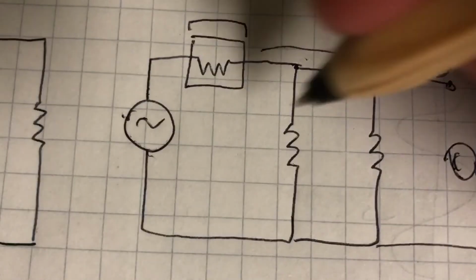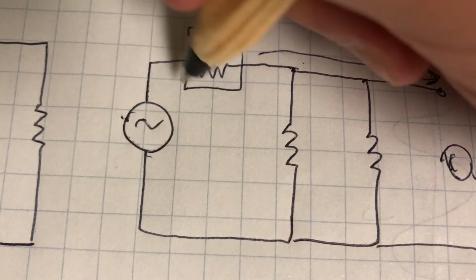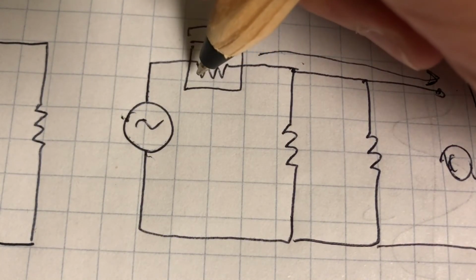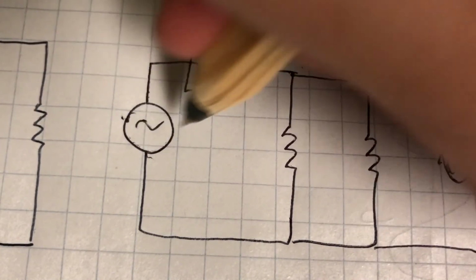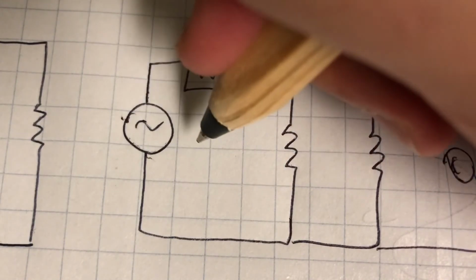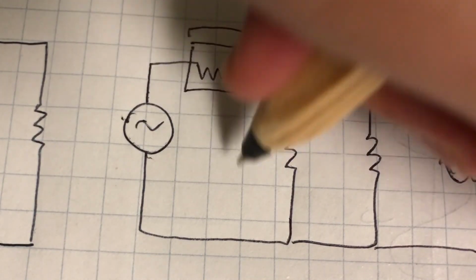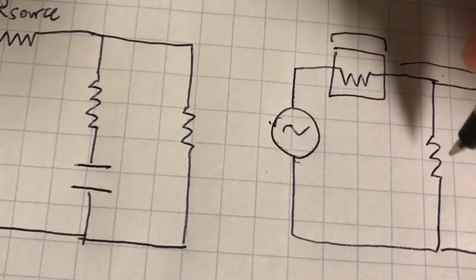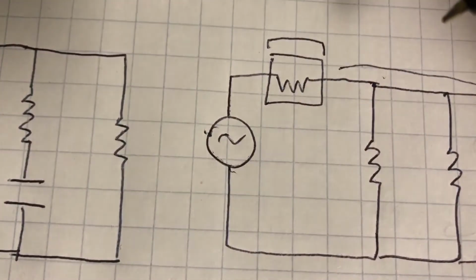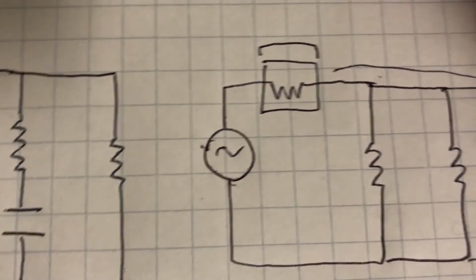Okay, and again, this is because a lot of it was dropped from this resistor over here due to the overall high amount of current flowing through it. Okay, and that's because the capacitor is charging up. Okay, so let's see what would happen for a low frequency.